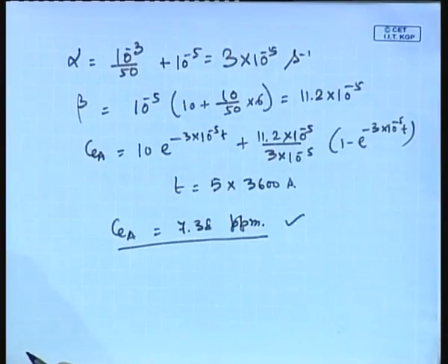But the point is, the stability of the liquid membrane has become a problem. It is really difficult to have stable emulsions beyond half an hour, 45 minutes, or 1 hour. I am saying 5 hours for this particular example, which is too large, too optimistic a value. Generally, the emulsions are not stabilized to that extent. So, stability of the liquid membranes is one of the major problems that hinders its widespread industrial application.